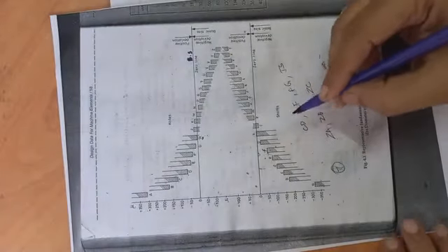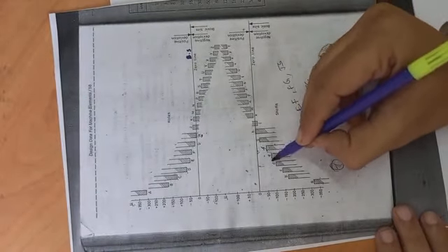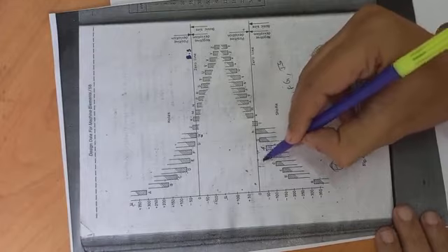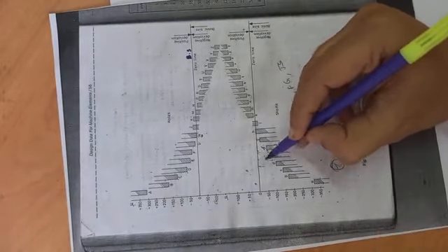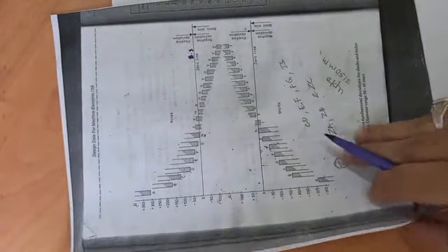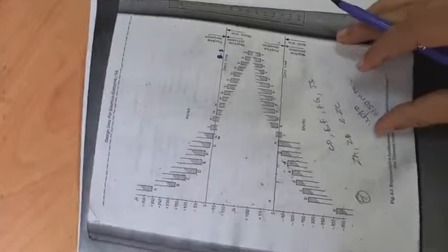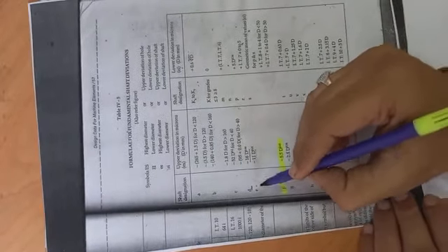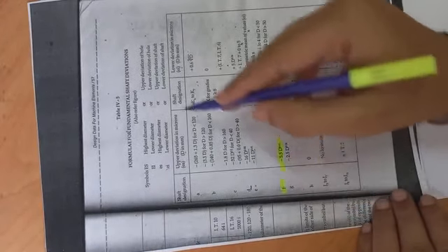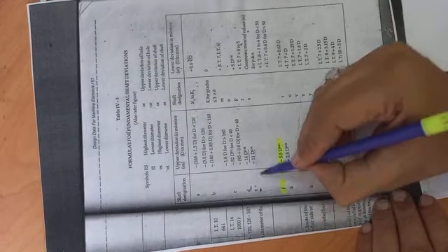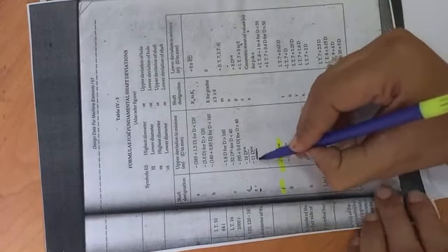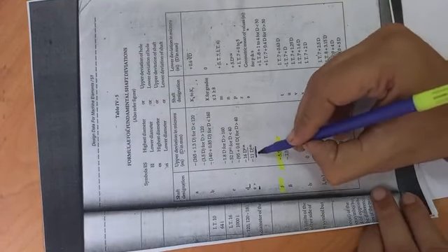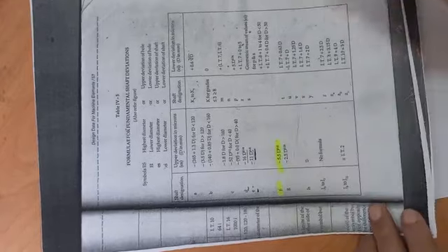For E type of shaft there is a fundamental deviation, and that fundamental deviation is to be calculated from this formula for fundamental shaft deviation. For E type of shaft, the fundamental deviation is to be calculated as minus 11 D to the power 0.41.